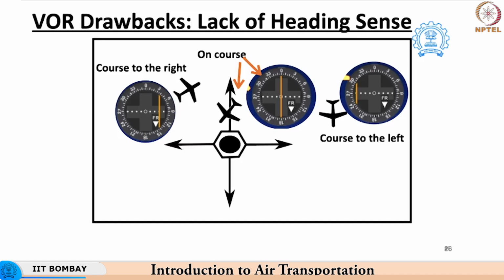As time passes, the plane has intercepted the pre-selected course and is showing a 0-degree deviation, but it still does not indicate what the overall heading is, and hence it can create confusion for the pilot as to what heading he is supposed to follow. This type of anomaly is also very crucial for aviators to take note of while making use of VOR equipment.